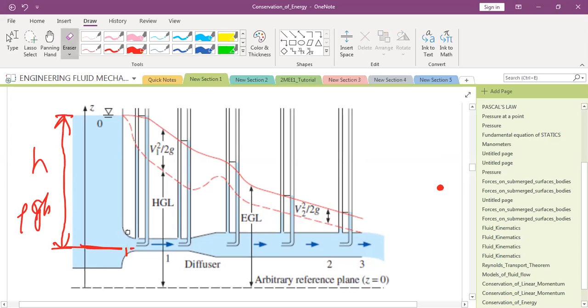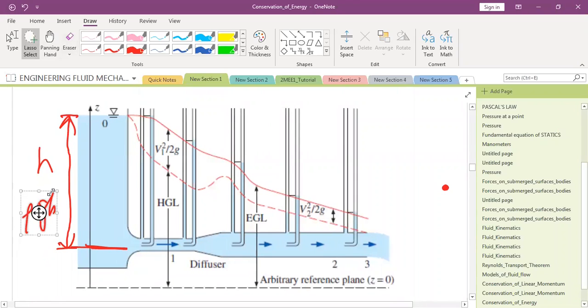So I have opened up this valve. Now you know that this is the pressure energy, this one. This needs to be conserved if there are no viscous forces. Although this will reduce if there are viscous forces, but this will be the same if it is an inviscid region of flow. So what happens is, now this is a static tube.